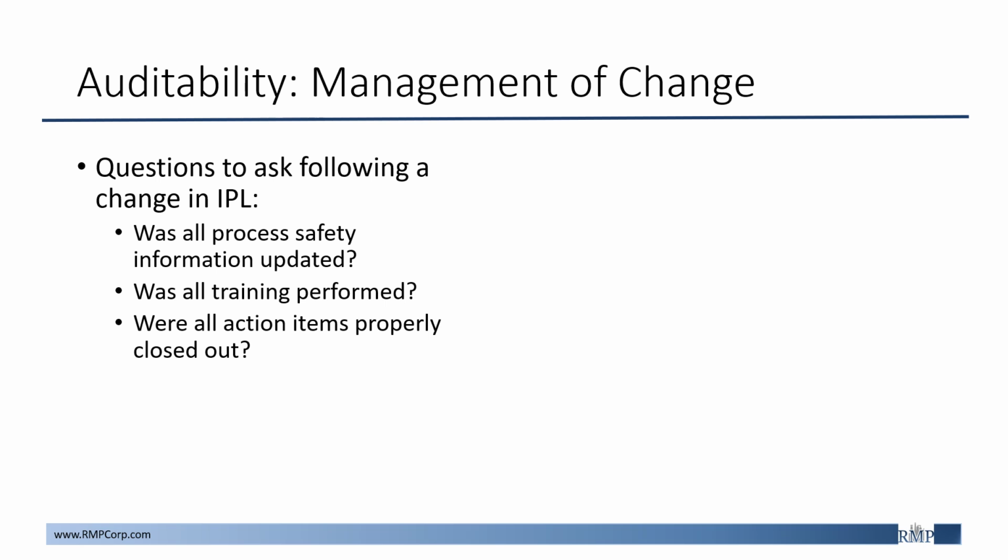So as an example, an alarm that's credited as an IPL may rely heavily on your operator intervention with a described operator response prompt that they see at the board. So if this operator response is changed and personnel is not properly trained on this change, this could result in the IPL no longer being credible, as the response may not be adequate in preventing the consequence from developing.